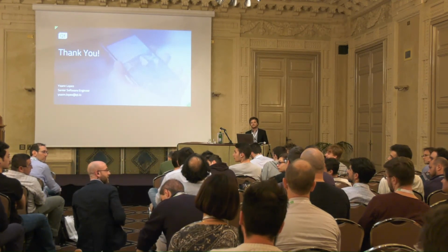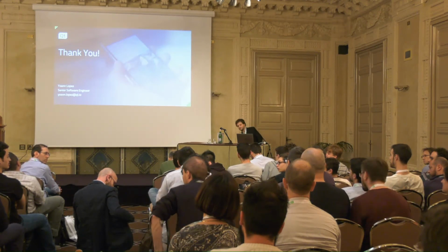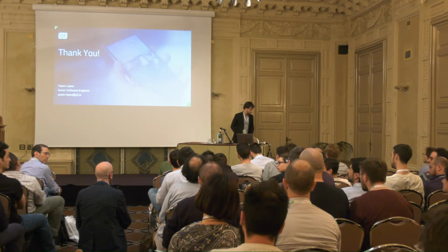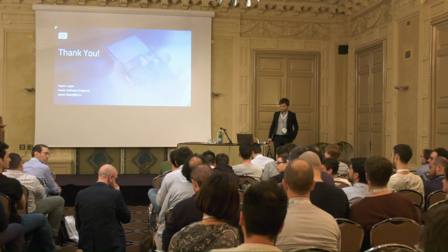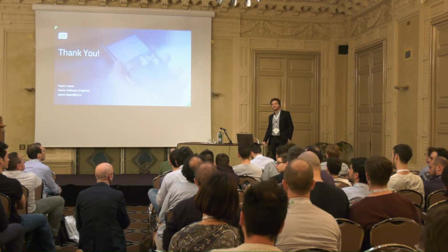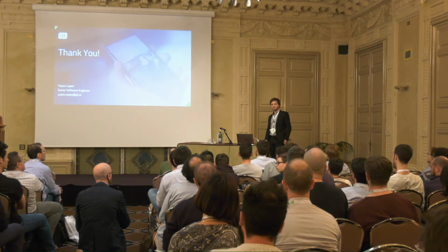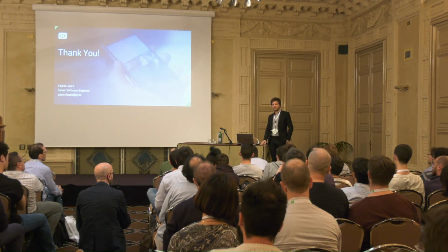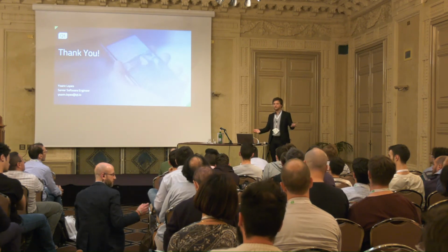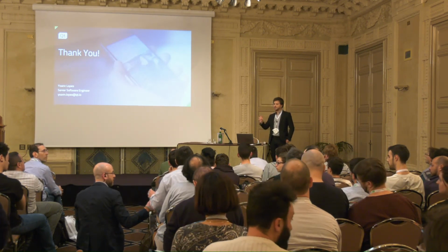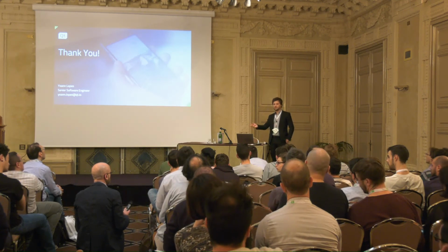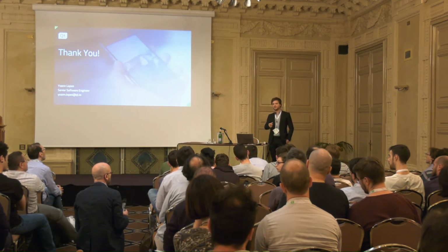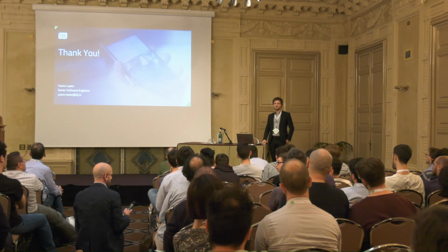For the part of exporting assets from Photoshop, do you need a plugin? So from Photoshop to Design Studio? Yes, this is what I showed you in the beginning. In Photoshop, you need to install a separate plugin to be able to export. Without that, you cannot really do anything. So it's a kind of two-step export. First you export from Photoshop with that plugin, and then you import inside Design Studio.